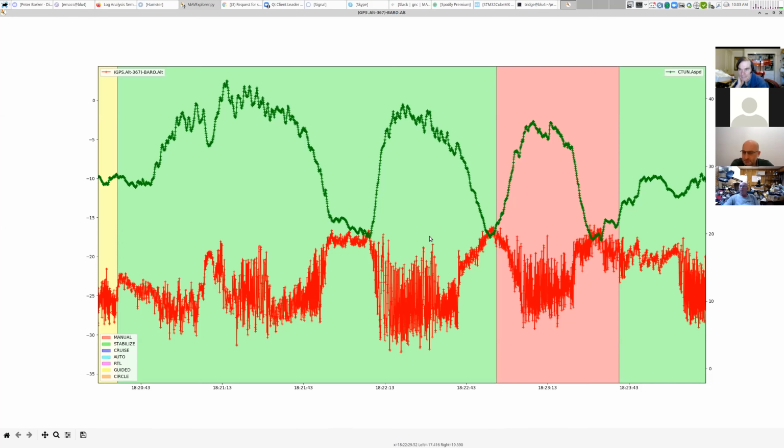and if there are openings, sometimes you get a point where some planes will get to a certain speed, and you'll start to hear a whistle from little gaps and slots and things. And although a whistle can sound pretty nice when somebody's diving, a whistle indicates a very strong acoustic oscillation or pressure oscillation to get a strong sound, and that can actually be picked up into the baro.